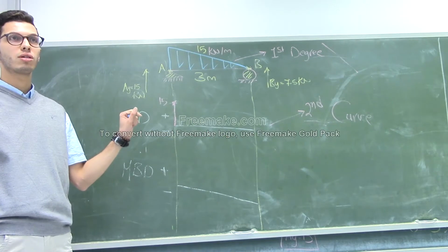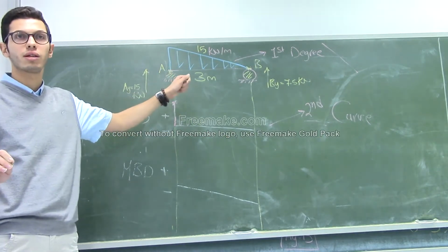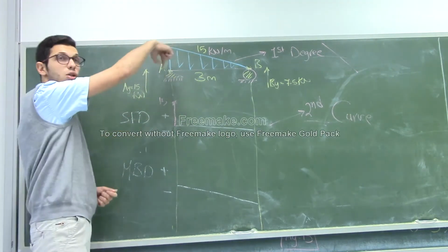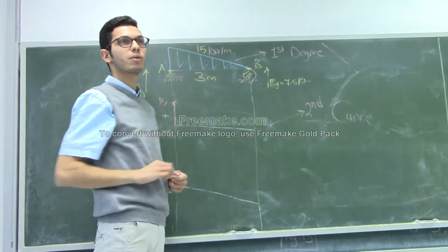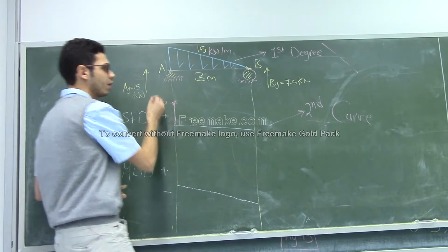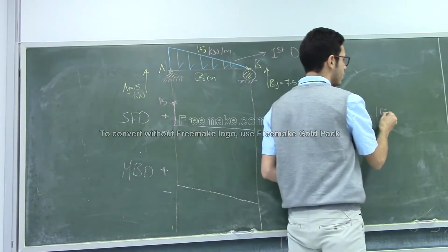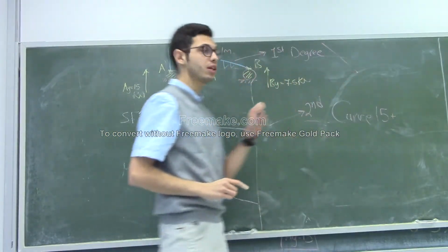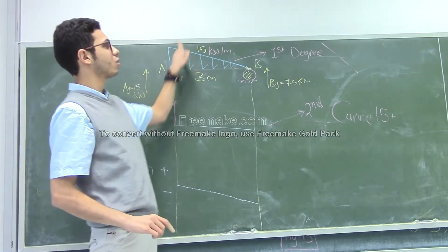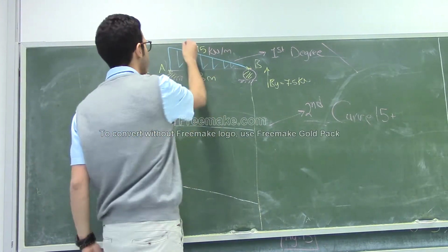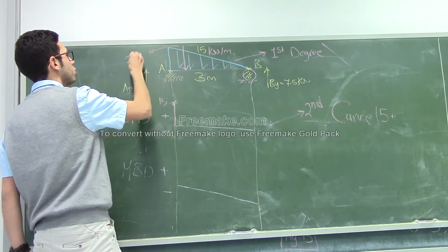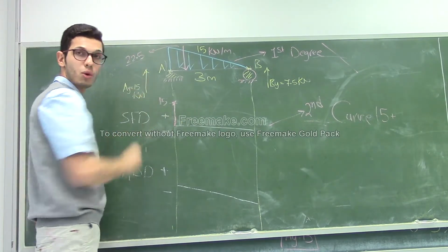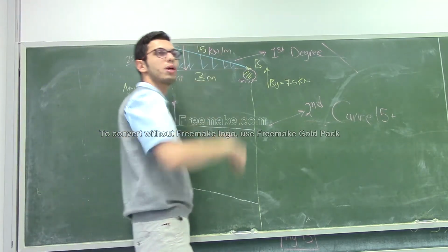Up to this point, all of you can understand this, right? Perfect. The direction of this load is downward. So I have a positive 15, I'm now here. And we find the effect of this load, approximately here. It was 22.5, and it was downward, and downward means a negative sign.